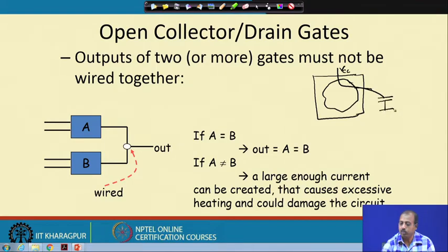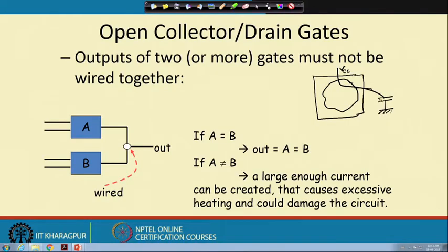The load is generally shown as a capacitive load, because a charging current is necessary for taking the signal point to logic high. The amount of current that can be drawn here is limited by the TTL logic family, so it is not very high. If you have to connect a large number of inputs to this output, it creates a problem.